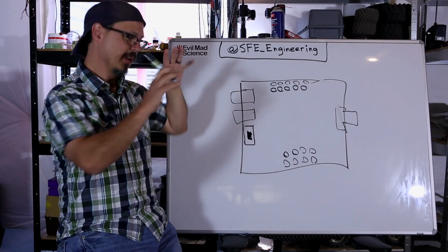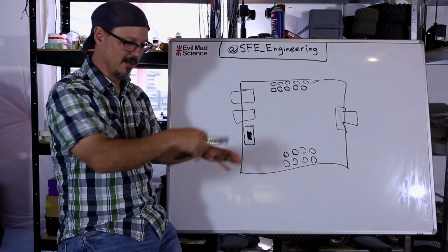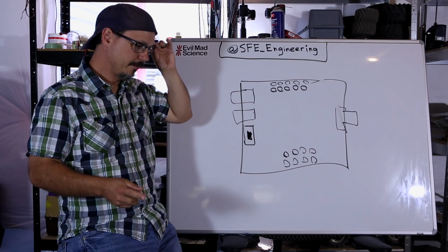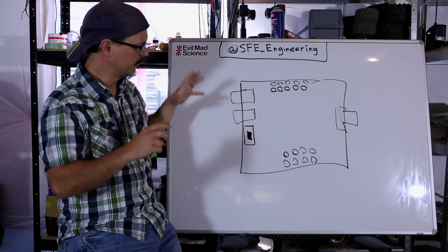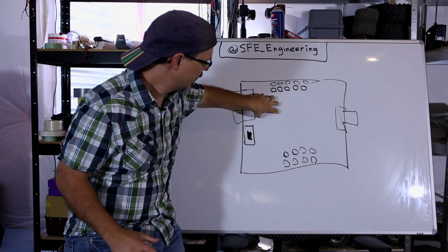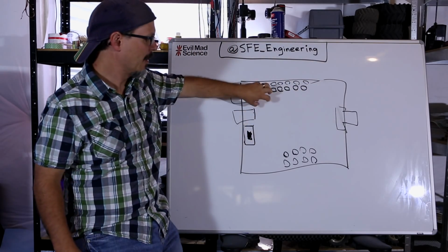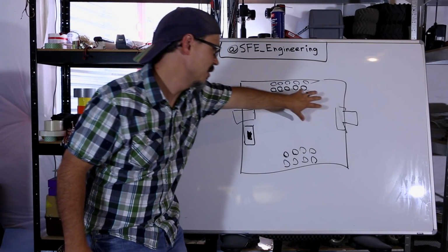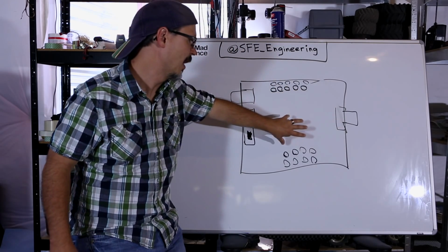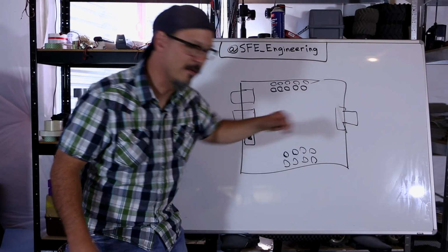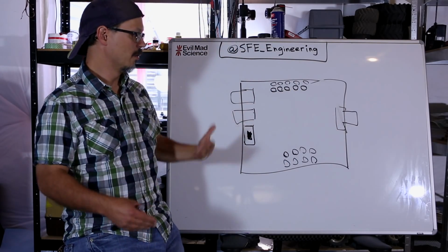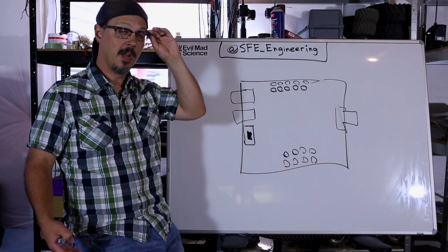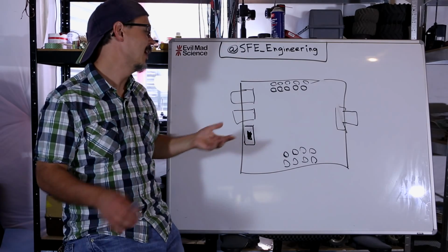Parts, individual. You've got a schematic, you've got a pile of parts to put in your board, right? The sections of the circuit are going to be arranged on the board, like you've got a power section, an amplifier section, a microcontroller section, sensors or RF, right? And these sections are going to be placed on the board according to their position in the signal chain, okay? And they all have signal chains of some kind, right?